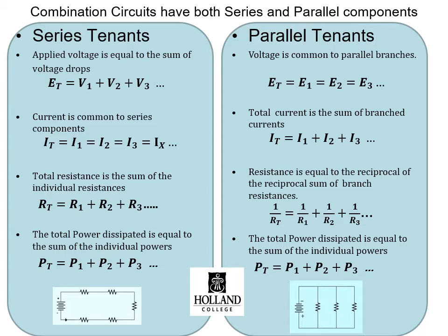We have to have these two basic principles for series and parallel clearly defined by this time. You must always keep these two things separate. The series tenets must always be kept for only series relationships, because they only apply to purely series relationships. So too with the parallel tenets. These parallel concepts, principles, or ideas only apply to purely parallel relationships. You cannot mix the two. And as long as you keep these two things separate, then solving a combination circuit can be quite easy.